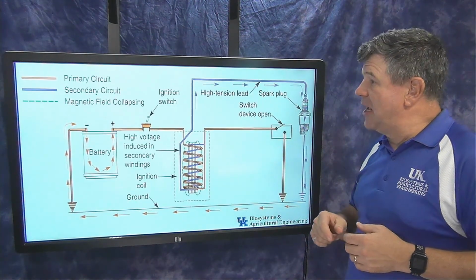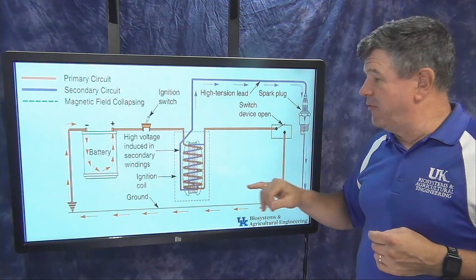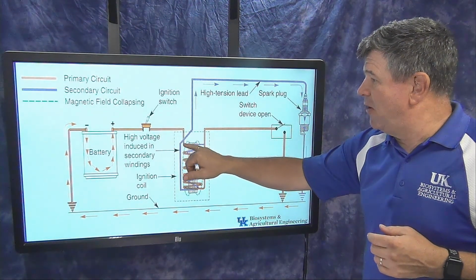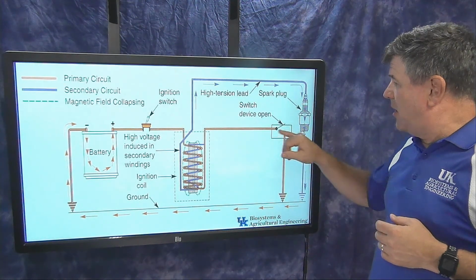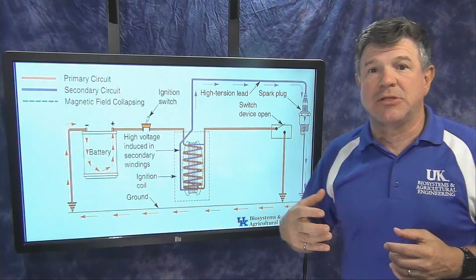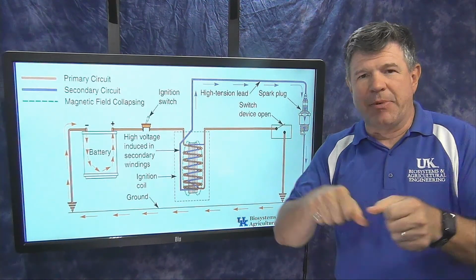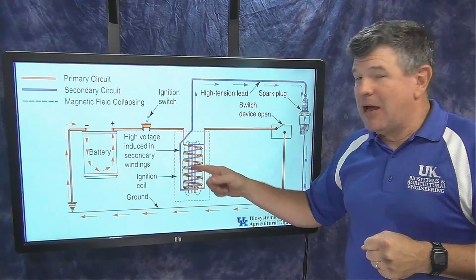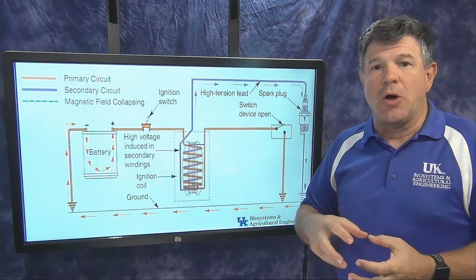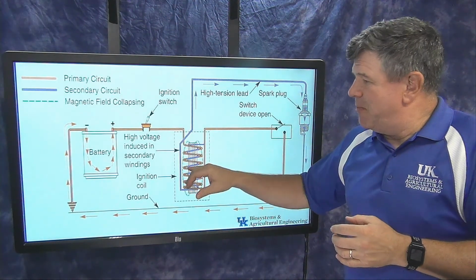So let's look at that example. Same system here. We've opened this switch device. Now when I did have current flowing through this coil and going over to ground, it can't go. So all that current stopped. And we said, what happens when I've got that inductor and all of a sudden I stop it? That's that speaker pop when you plug a microphone in and out or whatever. And we get that big high voltage. Ooh, there's a big high voltage, that momentum, the inductive kick.